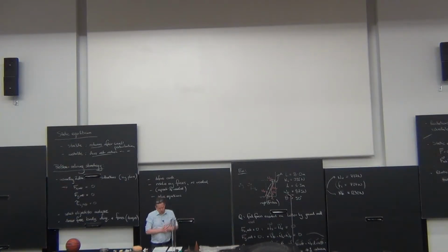Okay, good. So let me just briefly say a couple of words about center of gravity as opposed to center of mass. For us, center of gravity and center of mass are always going to be the same point. Center of mass is kind of the position-weighted mass distribution of an object. If you have calculated the center of mass of an object, its position-weighted mass distribution is 0 around that center of mass point.